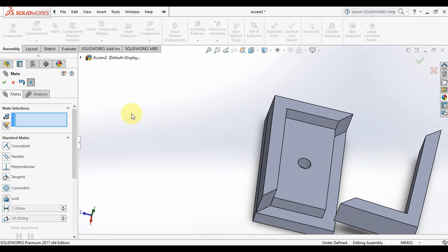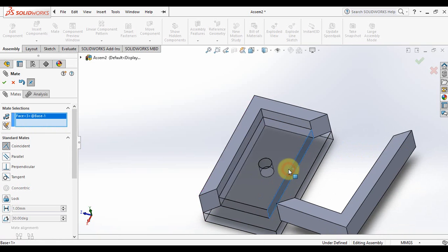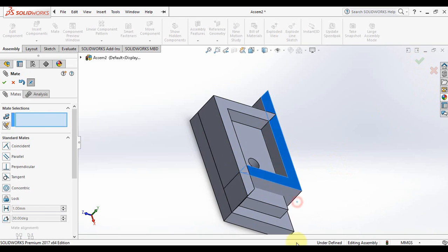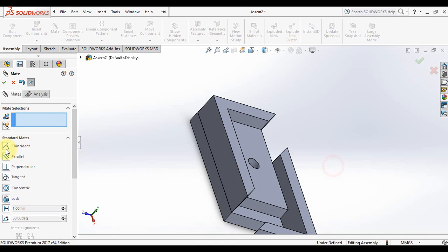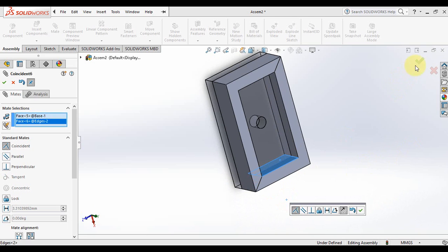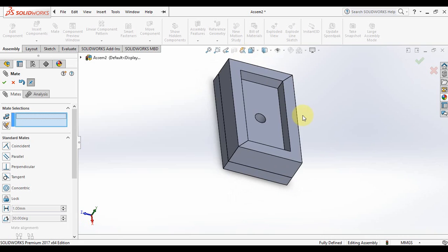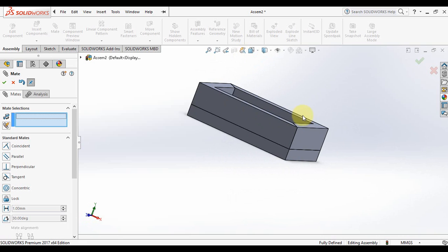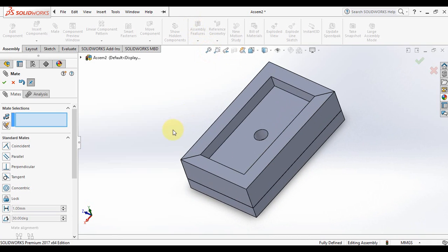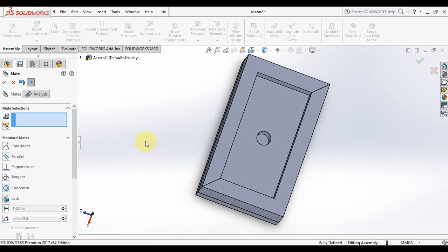So then I'm gonna say, okay, coincident between this surface and this surface, and again I'm just missing this one, so it will be coincident between, one second, between this surface and this other surface. So right now I have a box, basically. What's the idea? This box is made out of 3 different parts, so if you're going to print that, now you're sure that all parts will combine and it would look as you want, basically.